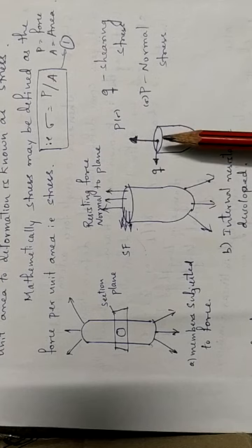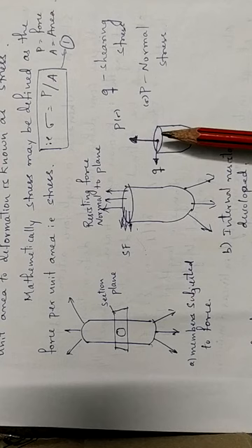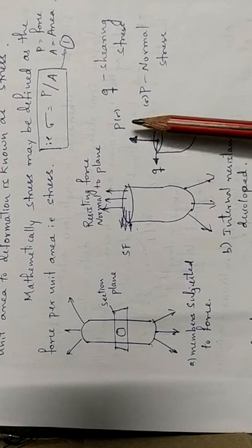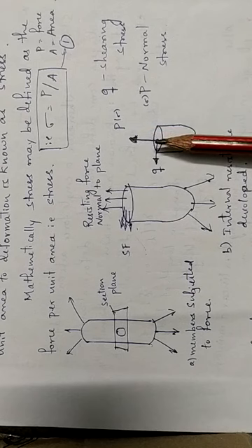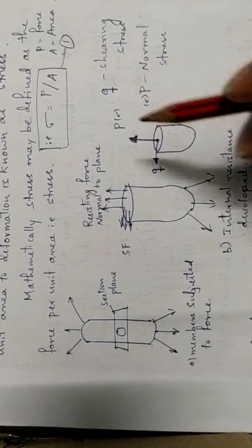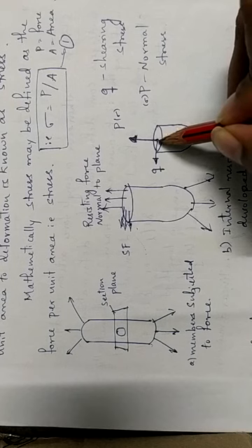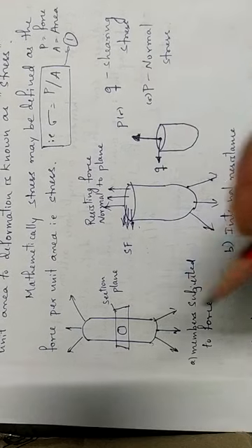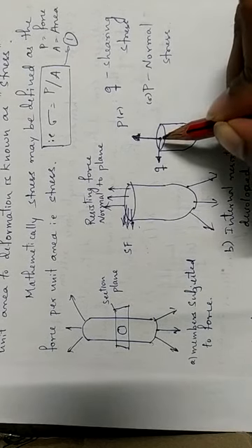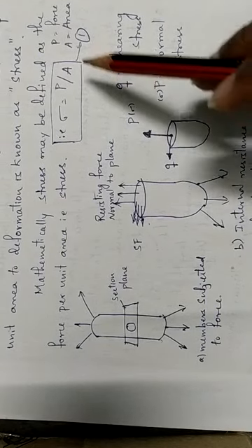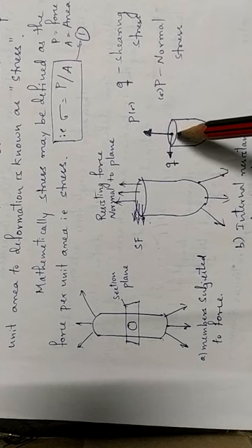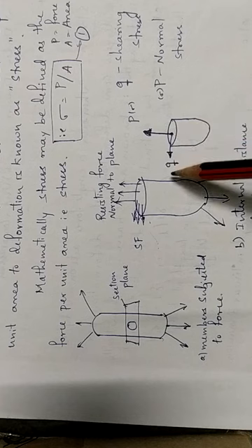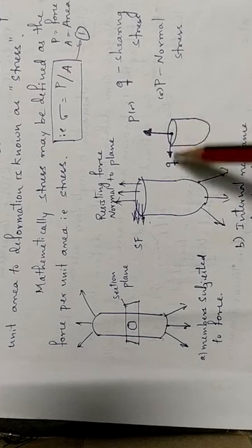Similarly, P is a normal force, and with respect to stress it is load by area. This load is acting on a unit area. Remember that the unit area is very minute. It is the force per unit area. Therefore, the force is either normal to the section plane, or with respect to shear force it is parallel.